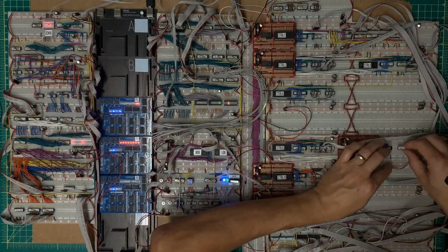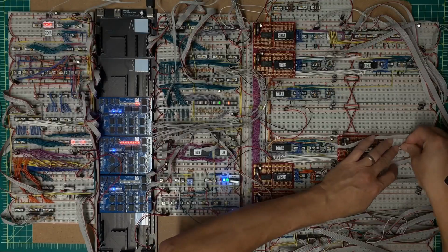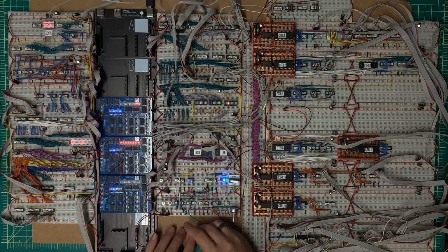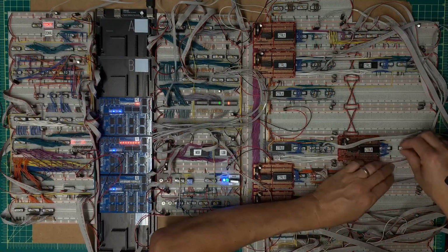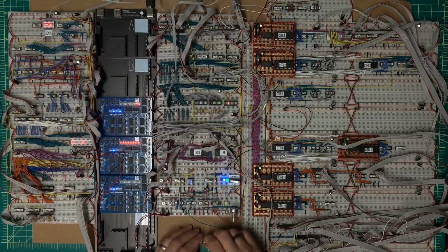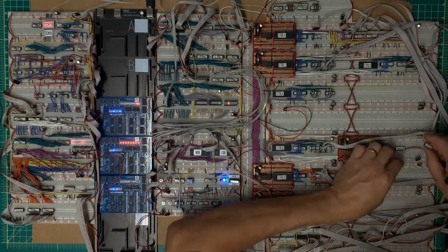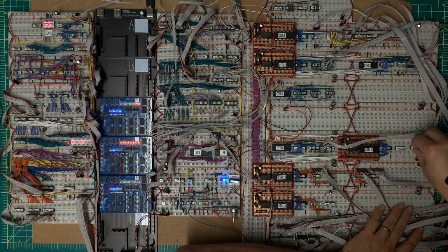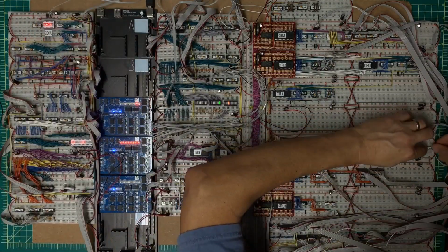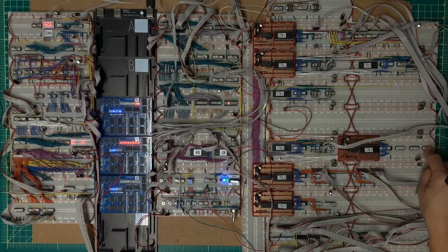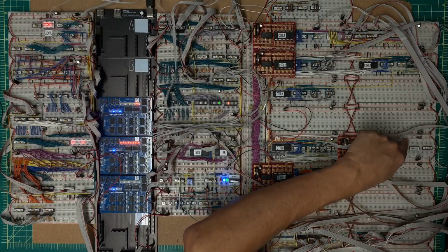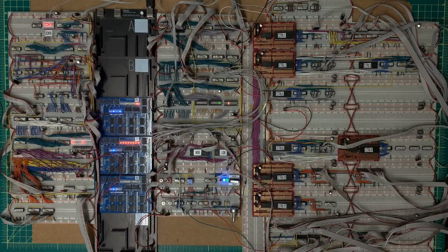But what I am able to do is drop in the NAND gates I need for the interrupt flags latches. And I happen to have these prepared. I think I had them placed in a previous video and I removed them. But I can add an AND gate at the end out here. And then this now becomes the place where I shape that signal. Now, 1, 2, 3, 4. So I can still pick up my signals here like I normally do.